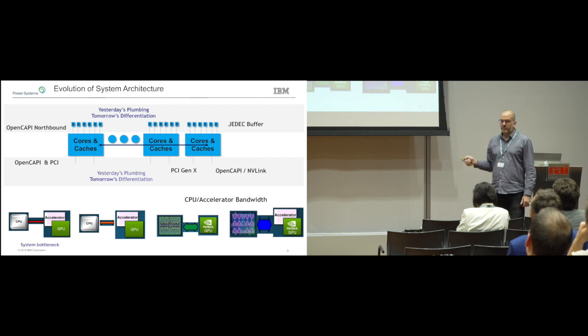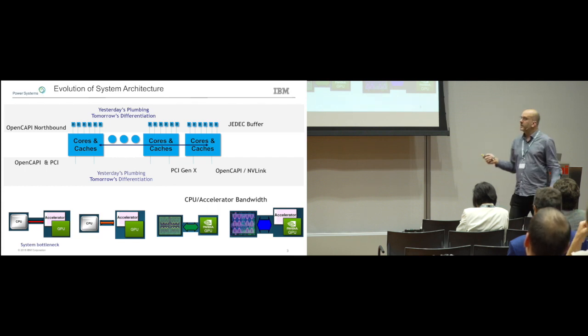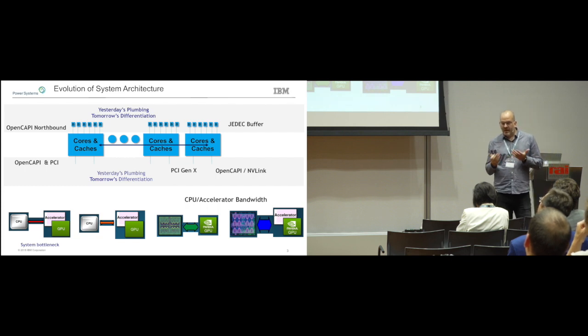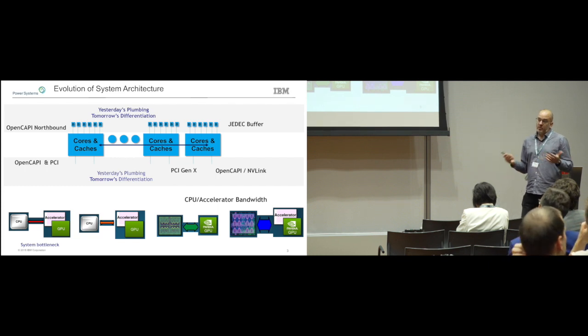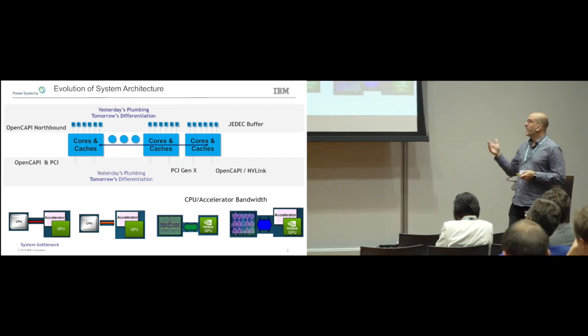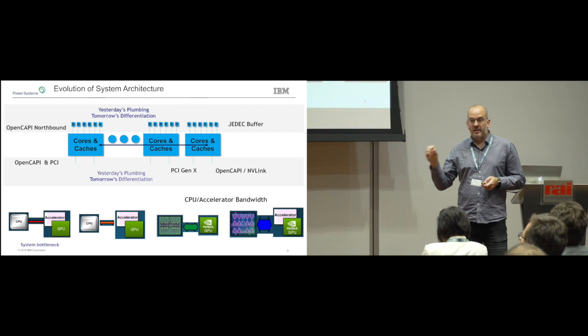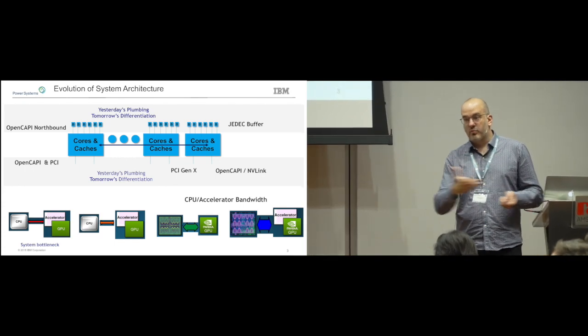I definitely think that's true. It used to just be DDR memory, with no real way to differentiate, though we did. Historically, IBM has differentiated on memory with our buffered memory solutions. We've been doing buffered memory for a long time to give us capacity and reliability out of what is really a commodity DRAM chip that goes across a broad range of computers.